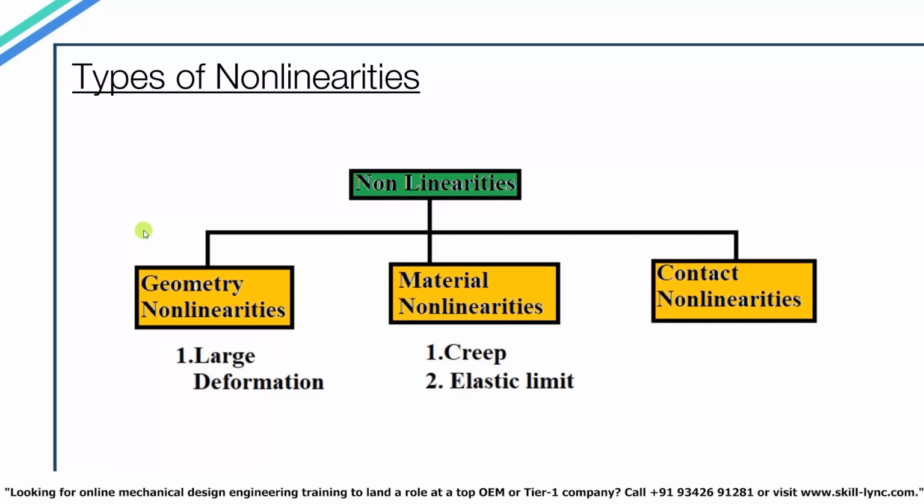In SOLIDWORKS, even if you go for a linear analysis and if the software detects any large deflections during the course of the simulation, you will be notified about it and will be given an option to switch to nonlinear analysis to get an accurate result.